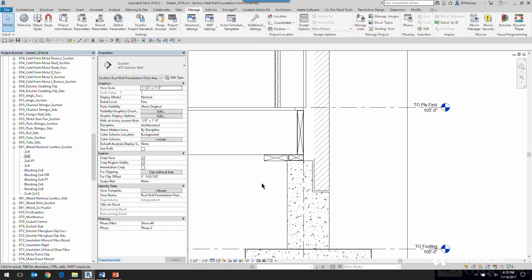What the heck is 3D and what's 2D in this view? Does everybody know about this tool over here for display model? You actually get an option to display the model half-toned. So now you can see, as you're detailing, what's truly part of the model and what I have detailed.